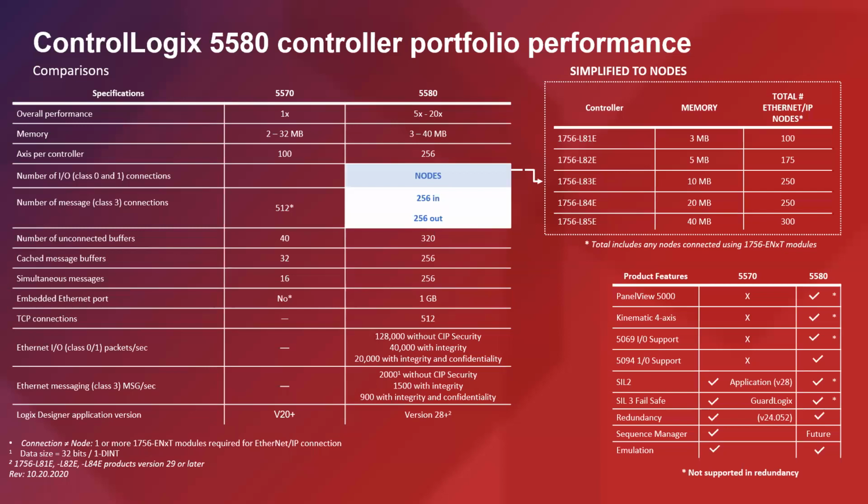In the L7 family, we look at the connections on Ethernet. This is going to Ethernet connections. So in some cases, some remote IO drops could take multiple connections, right? It's not just a simple, hey, one connection per whatever device I'm connecting to. Some devices took 3, 4 connections or more, perhaps. Whereas in the 5580, we're looking at the number of nodes. We're not counting connections. So we're only looking at how many devices are really connected there.